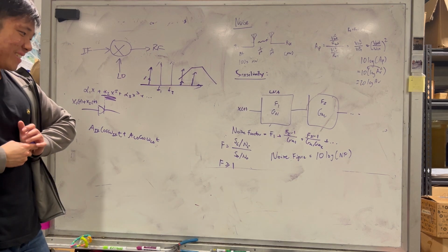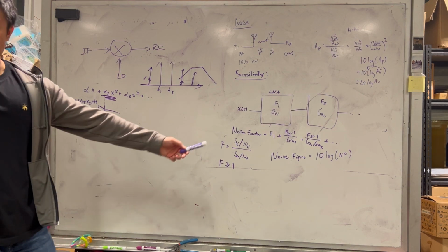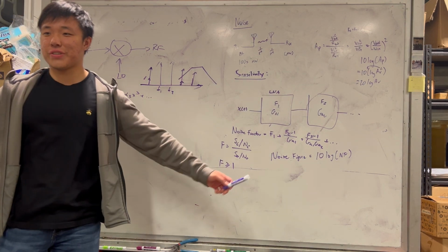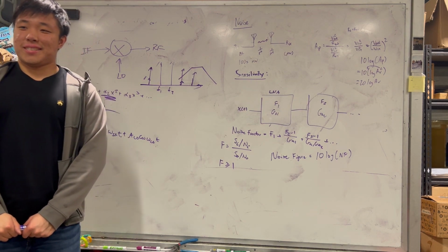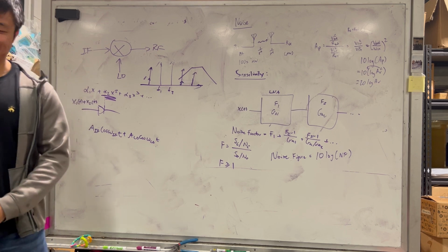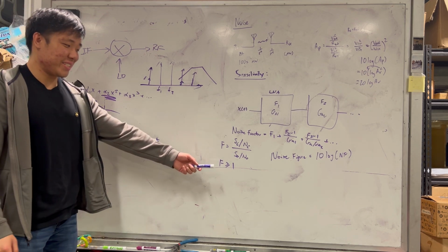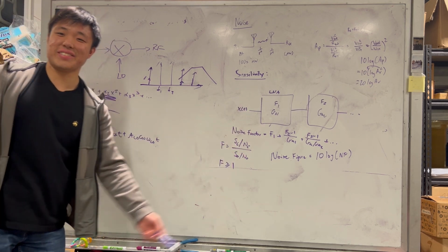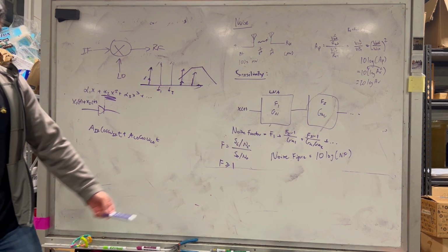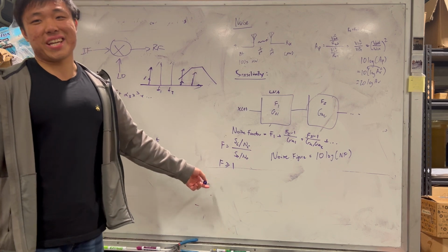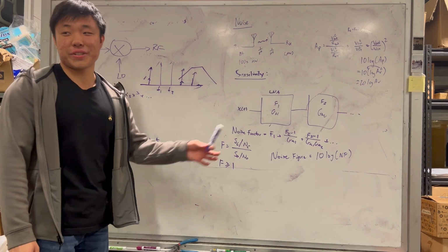So that means for noise figure, actually, what's the lowest noise figure I can get? 0. Exactly. So don't get confused when talking about this or that. When you see a noise figure of like 900 milli-dB, that's actually possible, because it's the noise factor that can't be less than 1. It's not the noise figure.